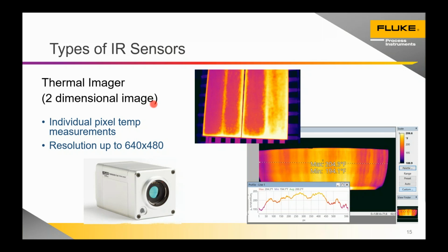In terms of the physical or spectral difference, our thermal imaging camera is what we describe as a long wave general purpose camera. It can be used for food, certain plastics, textiles, wood, asphalt. It can be used on metals with certain considerations regarding the point in the process. Generally, if you've got an application where you've got a decent amount of the metal in the air, it builds up an oxide layer. So it can be used in the steel industry too.